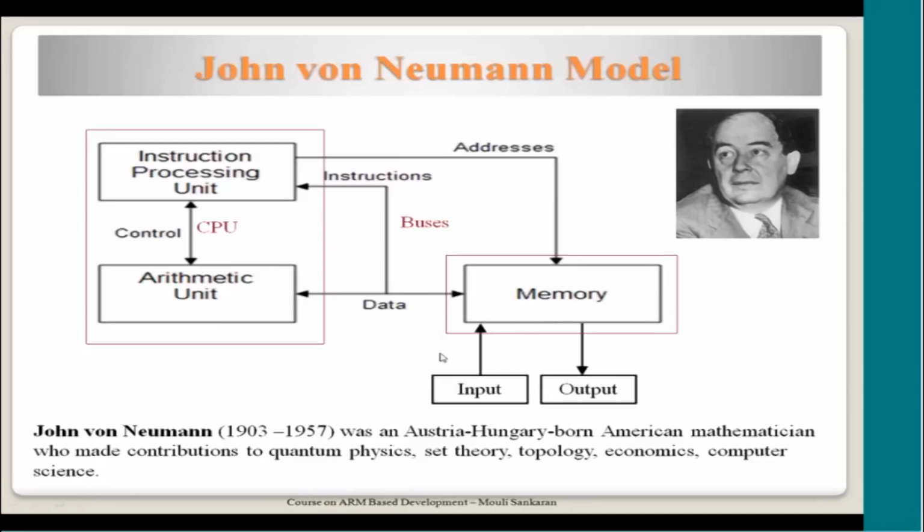As you see in this system, the limitation is that the same bus carries both the data needed by the software as well as the instructions to the CPU. Because of this, in a single memory cycle, both cannot happen simultaneously. As you understand, the instruction fetch and the data fetch need to happen together. And in this case, because of the limitation of the physical bus connecting the memory and CPU, they cannot go in parallel.